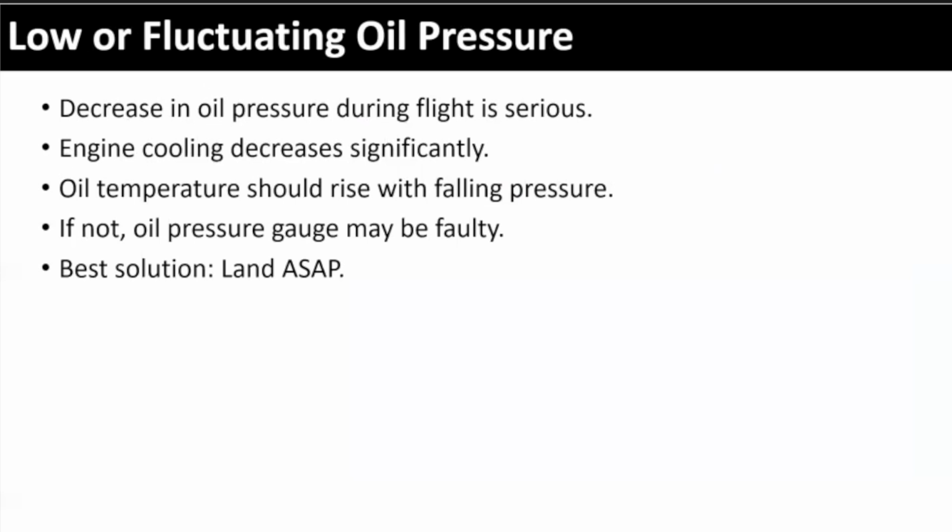Decrease in oil pressure. What does a decrease in oil pressure indicate? What could cause it? Oil leak. What else? Running out of it, right? Low oil. So what's one of the things on the pre-flight checklist? Check the oil. Every manufacturer, every aircraft and every engine is going to specify a minimum. Ours out here, if you go below 6 quarts, put a quart in it, right? Don't ever fly it below 6 quarts.